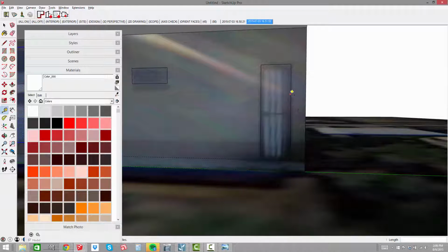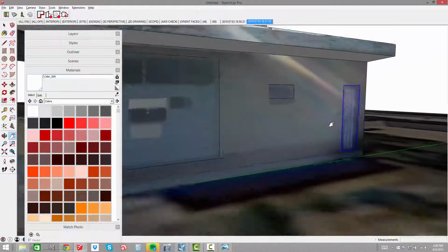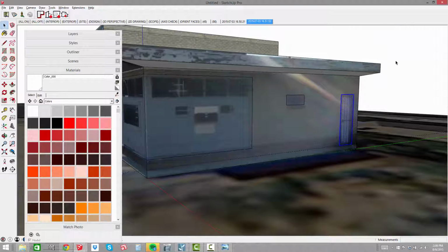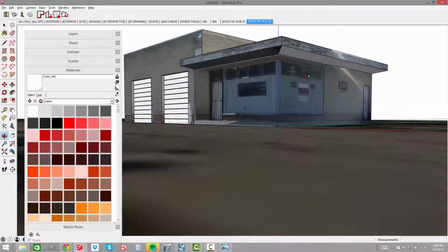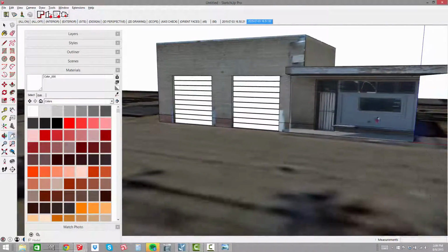This door, it's a little bit distorted. It's like 2'3". I might just take it and use my scale tool, finish the stretch, and then call it like 32 inches, enter. So that way it's a little bit more realistic. You know, we're not doing super precise modeling here. It's just intended to get the broad strokes down. Okay, so we're looking pretty good.